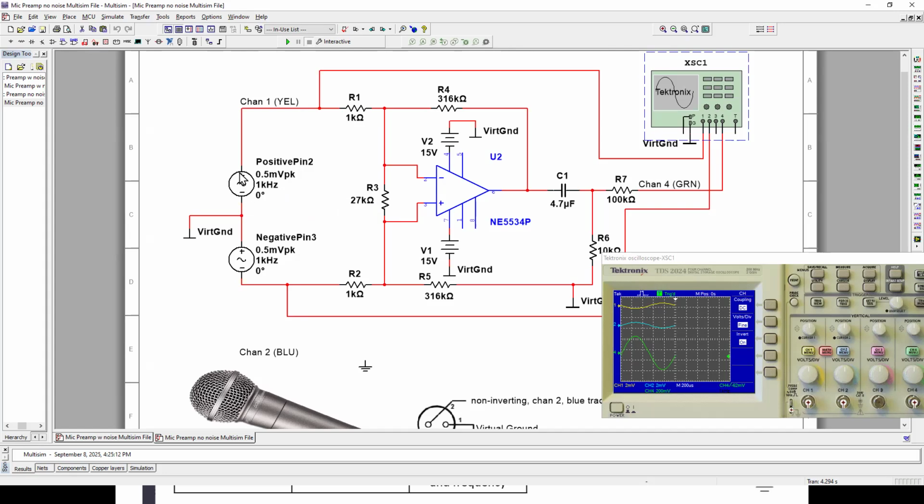Those two cables are going to be affected the same way, because the noise in one wire is going to be in phase with the noise in the other wire. So they're both going to rise at the same time, and that is going to be ignored. That's why it's called a balanced line, because we have three pins. One signal goes one way, one signal goes the other way. It makes it a balanced line. It's called a balanced audio line, for example.